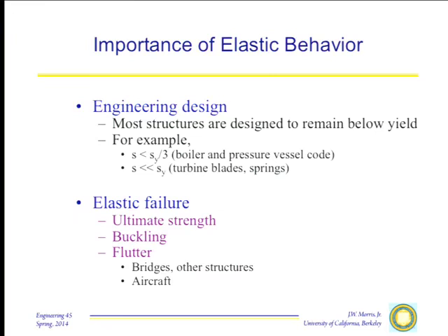The Lockheed Electra, by the way, is still flying. It's the Navy's P-3 Orion, which is the primary search plane. A lot of the searching for this thing down in the South China Sea and the Gulf of Australia is being done with P-3 Orions. That's a flutter failure. These are failures that are elastic in nature. You can break materials without ever calling their plasticity or even their fracture toughness into play with these elastic failure modes.